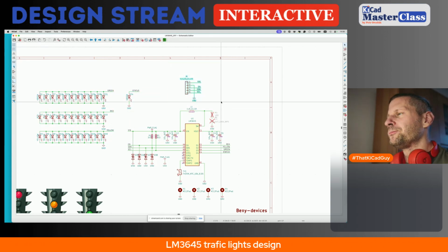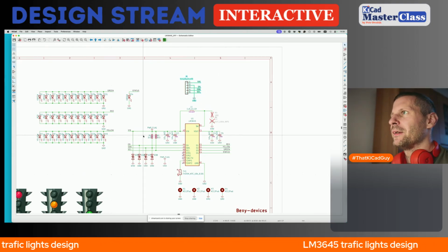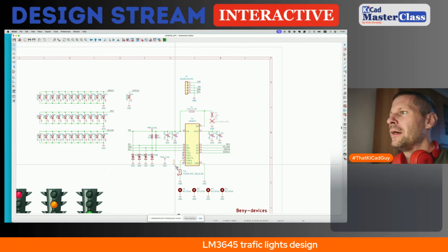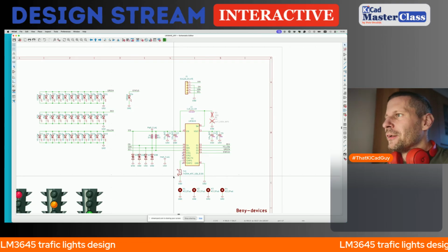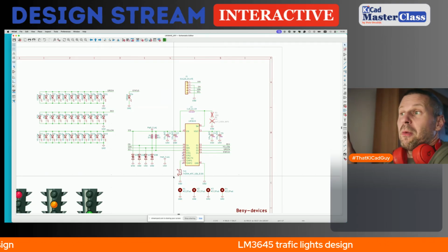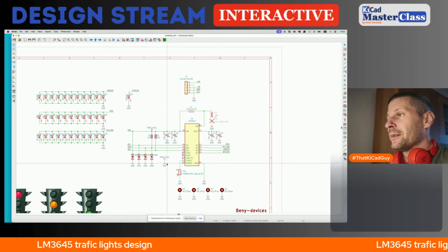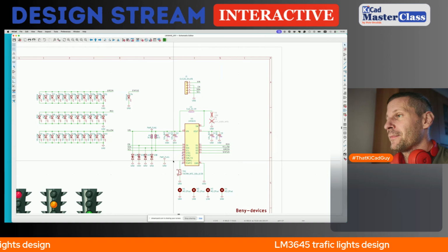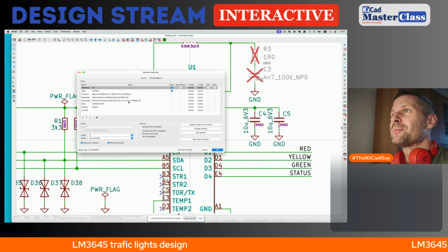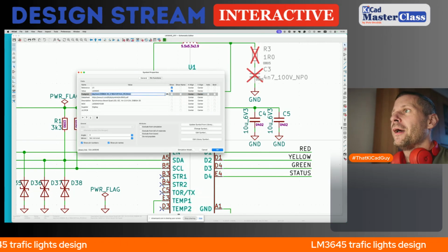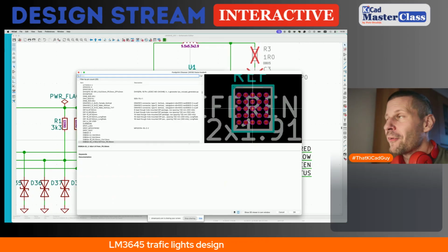This is a system connector with I2C, enable pin and input voltage along with the ground. Here is the thermistor sensing the temperature of the IC and probably the board. We will see where we manage to place this NTC, the thermistor. Last time, if you didn't watch, I spent a significant amount of time thinking out loud how to fan out this really fine pitch BGA.